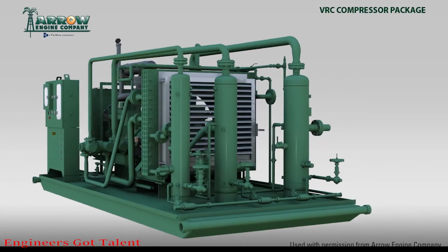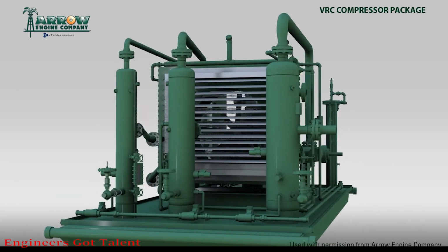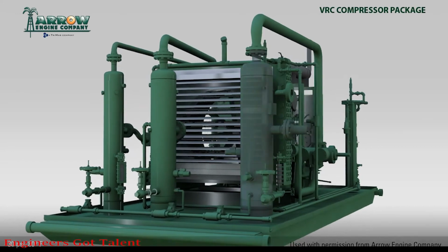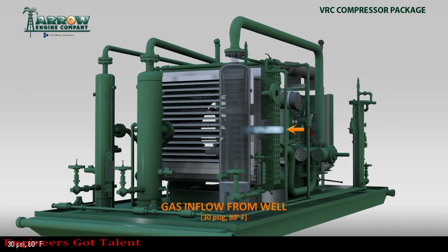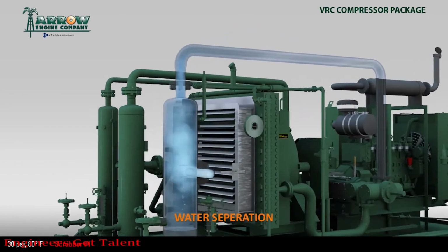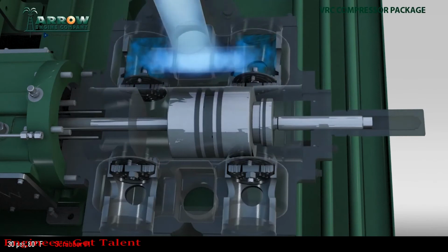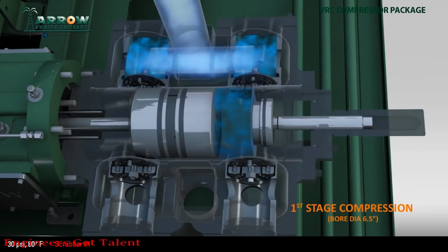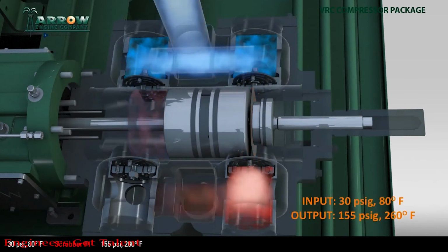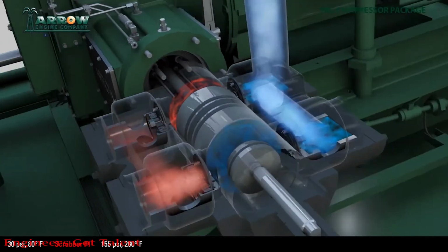This video shows the inner workings and the flow path of a three-stage reciprocating compressor. The inlet flow or suction side of the compressor starts at 30 psi and 80 degrees. It enters the inlet scrubber and any free liquids fall out. At the first stage of compression, the pistons will compress the gas to 155 psi and the temperature will increase to 260 degrees.